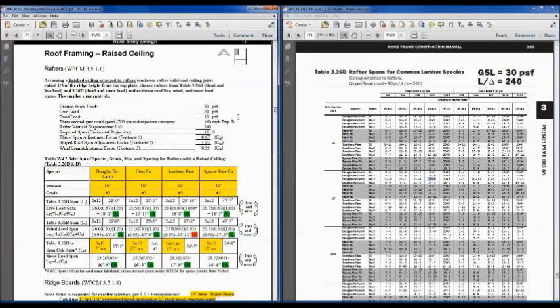Yep. And so in the wood frame construction manual, there's a whole section in Chapter 3 that says if you have a roof system that's to be a roof truss system, or a roof I-joist system, which is also used in some applications, those are per the manufacturer. So those are designed typically by professional engineers for those systems, and that's the way the code is written to address I-joist and truss engineered wood product type applications. We show rafter systems here just to give us a chance to use those requirements. We know some stick framing is still done in certain parts of the country, so we understand that that's not necessarily the predominant use in the country, but those engineered systems are designed by a separate manufacturer, typically a professional engineer with that manufacturer.